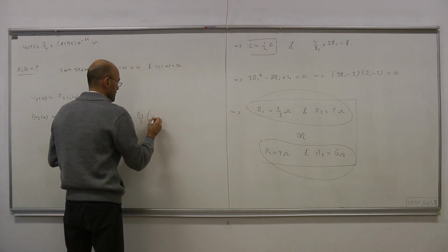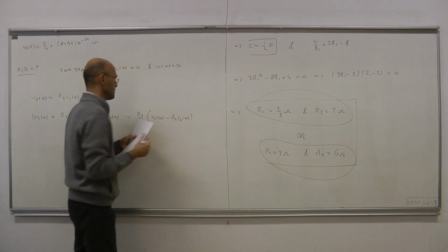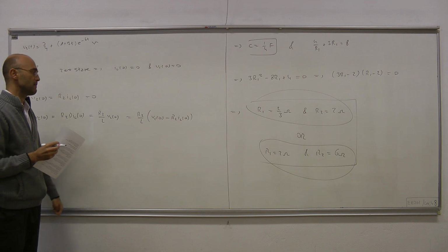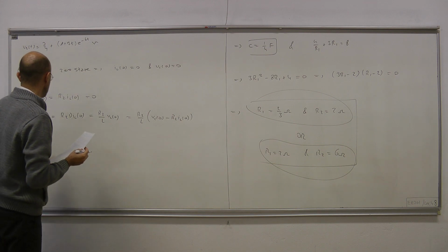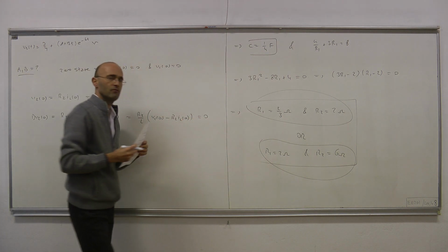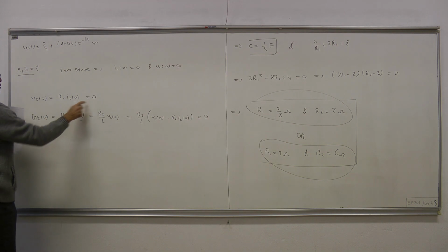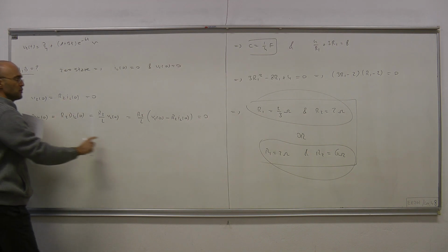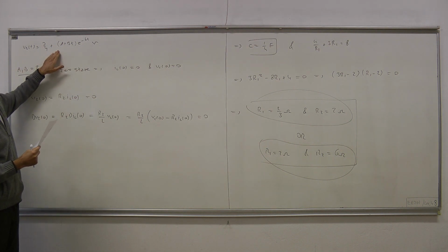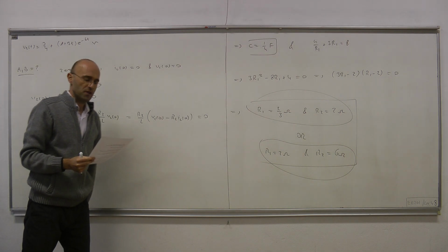So what we have is VC(0) minus R2 IL(0). Since VC(0) and IL(0) are 0 by definition of zero state or step response, hence dV2(0) must also be 0. Okay. Now we have two constraints, V2(0) equals 0 and dV2(0) equals 0, and by applying those two constraints to the solution, we figure out, hopefully, the unknowns A and B.